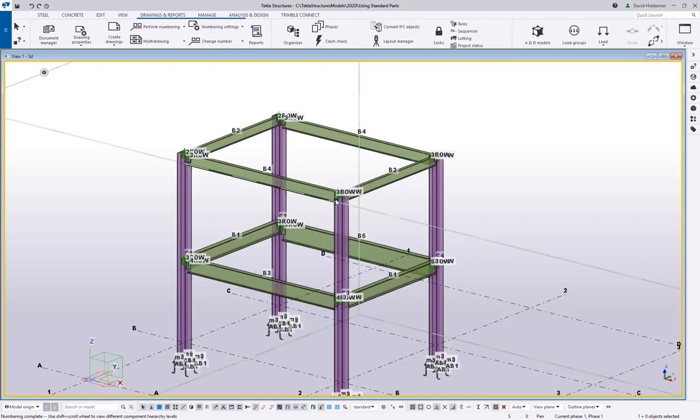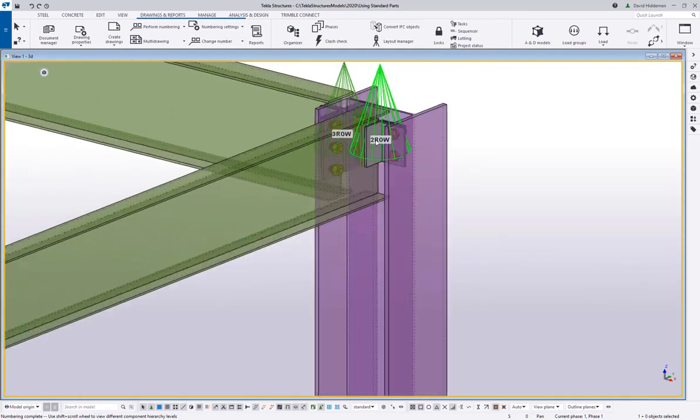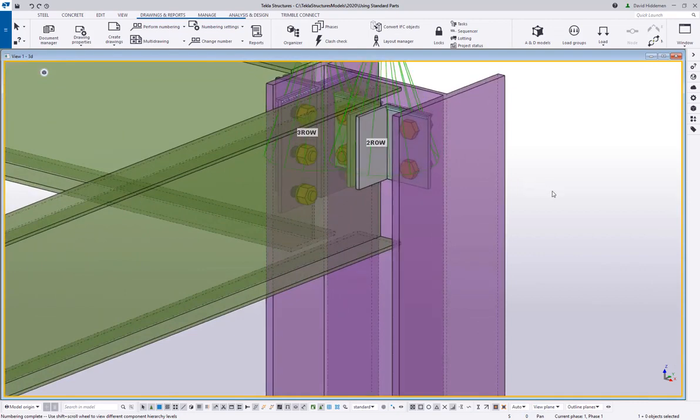So that's all it is. You set up a model with just a field of pieces. In the part prefix, you teach it what you want it to be. And then in your production models, you set up the file path and make sure you change that option in the numbering settings. It's important to note you do not run a numbering in that catalog model. You notice I did not do that. I simply changed the prefix, saved the model, and exited. So you do not actually run numbering in that standard parts model or catalog model.